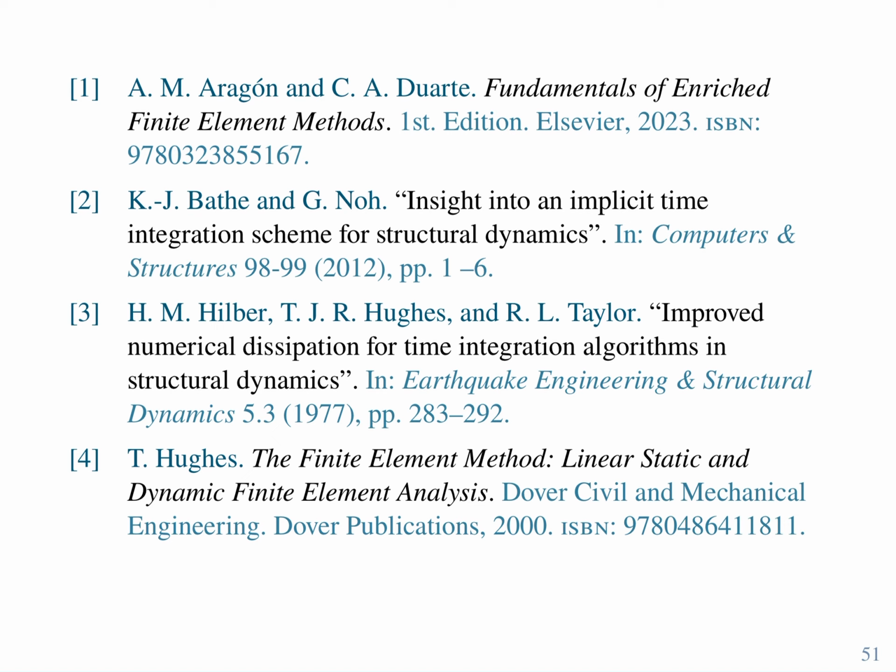Out of curiosity, do people also do stochastic time integration for finite element methods? Stochastic finite elements. Yeah, of course, everything we have described so far is deterministic, right? But you can bring stochastic approaches. You can say that now my Young's modulus is not just a constant, but a function that has a probabilistic distribution, a Gaussian distribution, and of course there are ways to incorporate this. Of course, then you get a response that is within some interval of confidence. So this is something that is widely studied. It's done. So yes, sure, there are ways to do that.